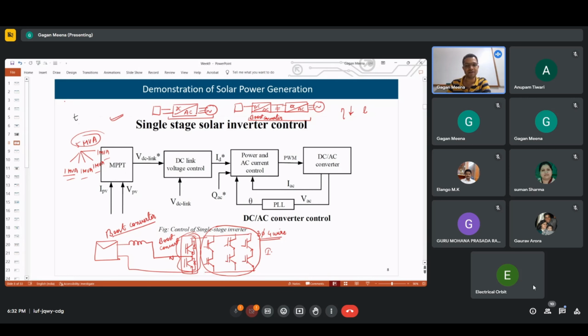Yes, correct. Because we are using resistance for equalizing the voltages, the battery current is taking a resistive path, so I square R losses will be the heat dissipation. That is going to deteriorate the capacity of the battery, because temperature will increase. It may increase the temperature to a very high value and it can lead to thermal runaway.